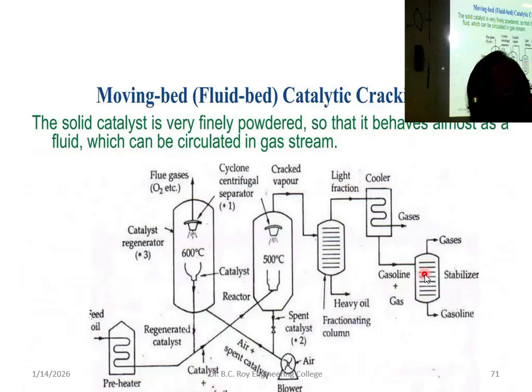So the timing is wrong and the position is wrong. Combustion is happening at the wrong timing and in the wrong position. That will reduce the efficiency of the engine and damage the engine. That is called knocking. Could you understand knocking?